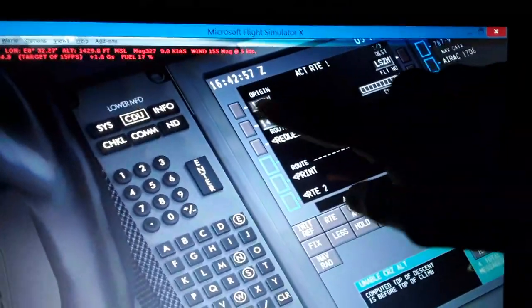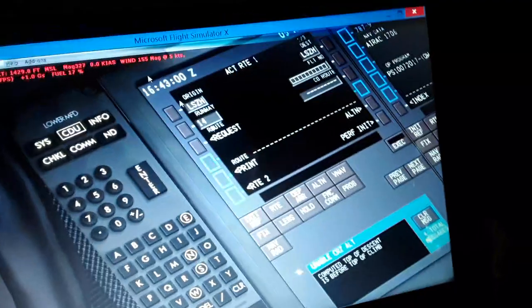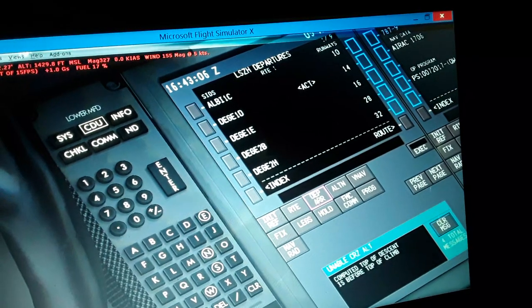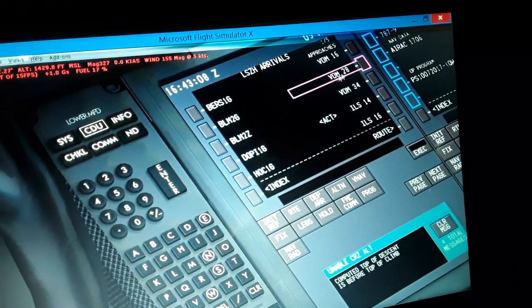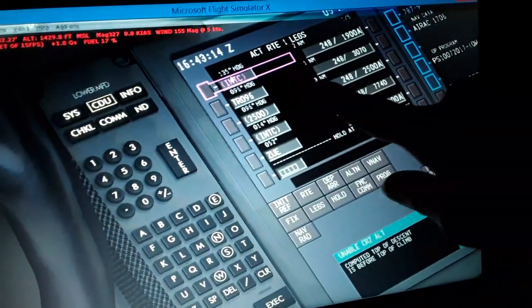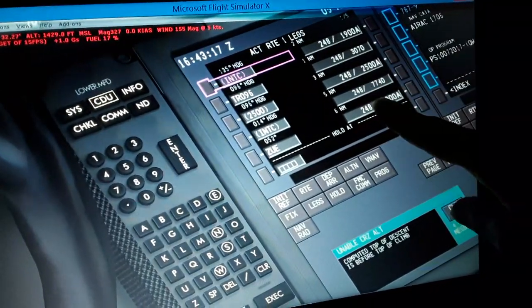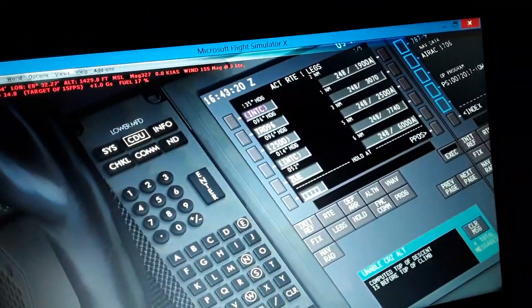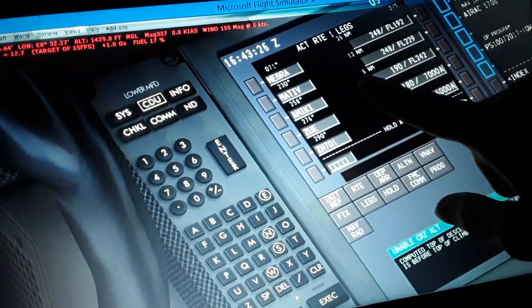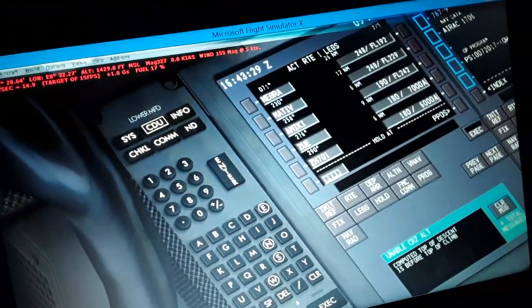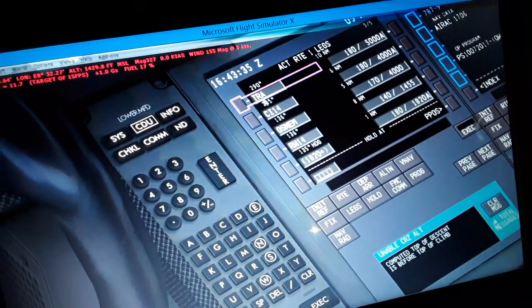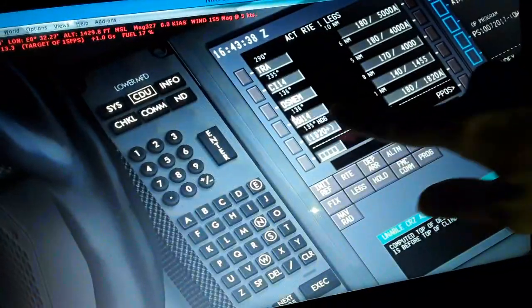The route, origin, destination, the runway we're going to use, Zurich International Airport, departures over here with the standard instrument departures, and arrivals with the STARs, the standard terminal arrival routes, waypoints and fixes, and the legs from takeoff, climb, cruise. So we keep climbing to 6,000 feet, heading of climb, next page, then cruise over here, Nitra and Mativ, then start the descent back to the level over here, 7,000 and 6,000 feet, and then we have the runway. We have to arrive here, runway 14.